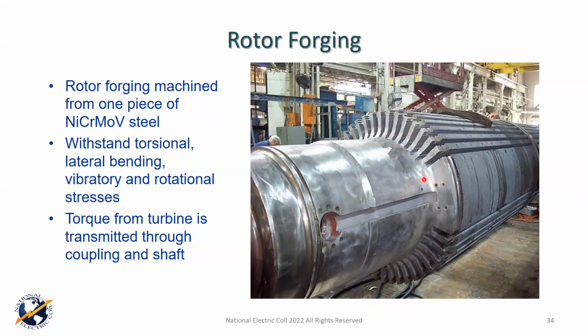Now, I will say this: in some very old machines, they used to have problems with the older steel where they got impurities that would cure in the center of the shaft. Going back 50, 60, 70 years ago, they had that issue. Today, the newer machines and most of what we would have in combined cycle applications really don't have a big problem with that. But we have more than enough other ones that we'll talk about as we go through. But anyway, this is the rotor forging.